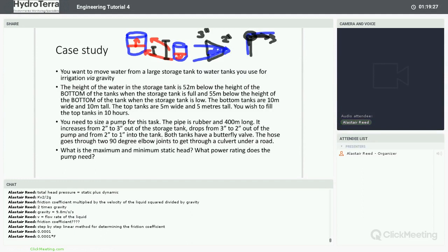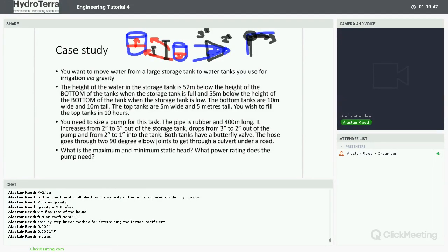How much is exerted by reducing or increasing the size of the hose diameter, as well as how much friction is exerted by different types of pipe: stainless steel versus plastic hose versus rubber hose. That's all put together to generate a dynamic head, which is measured in meters. And it's effectively how much extra height does our pump need to overcome to push that liquid.